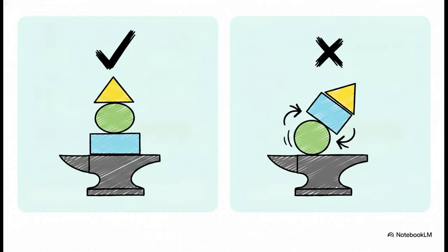So, why does that order matter so much? Well, if we have the exact same part, but we just swapped the primary and secondary datums in the callout, changing ABC to BAC, we've basically created a totally different set of instructions. The part is now physically fixtured against datum B first instead of A, which means a part that passes inspection under the first frame might completely fail under the second one, just because of how it rests on the table.